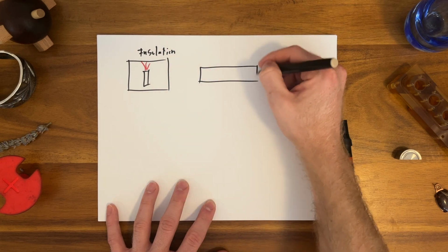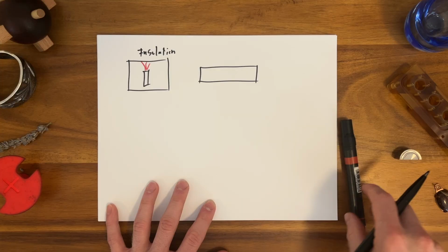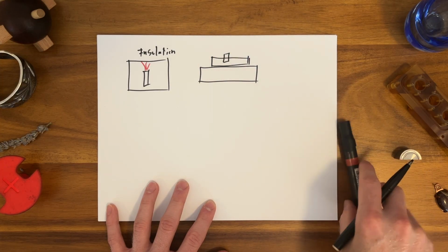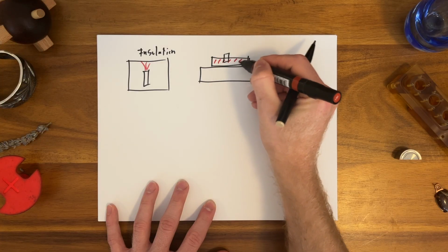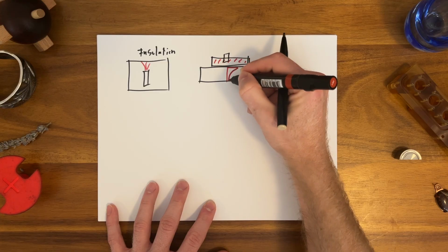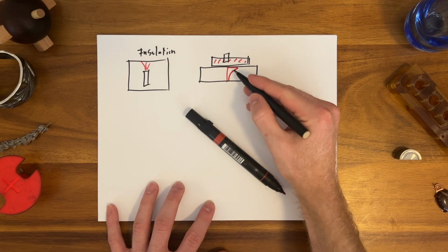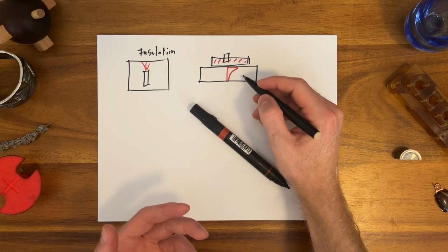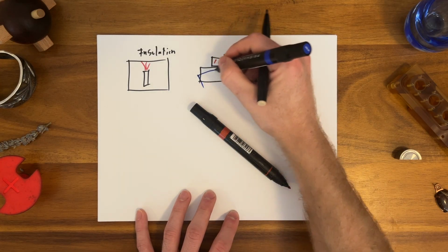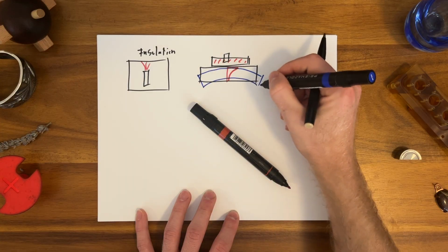In the precision machine world, let's say you have a giant granite block and you have your linear motor set up on top, moving back and forth. The linear motor makes heat. Essentially, you're going to drive a thermal gradient into the granite. The thermal gradient creates strain, it creates deflection. Your whole granite block is going to be curved. That is unfortunate if you want to make accurate shapes.